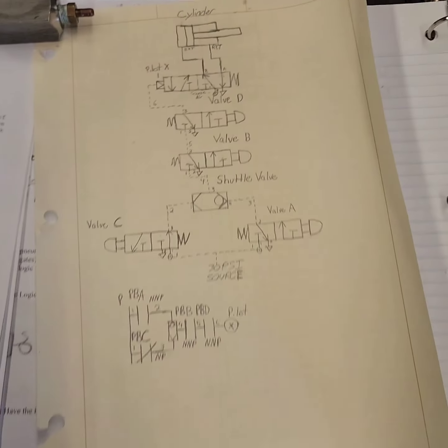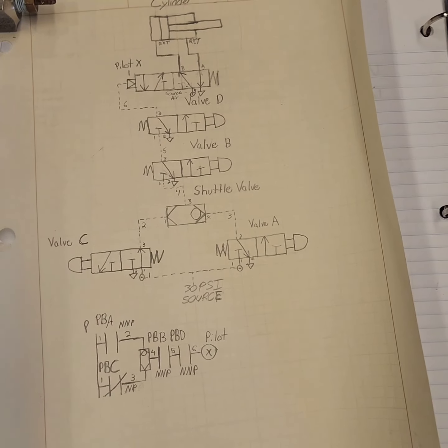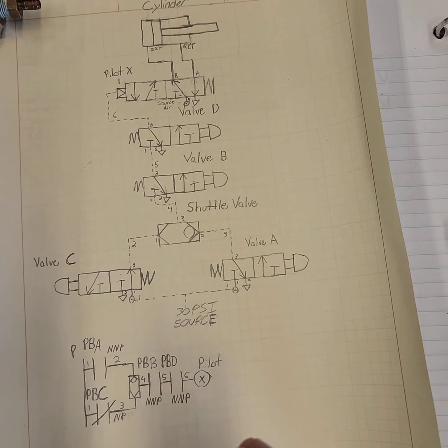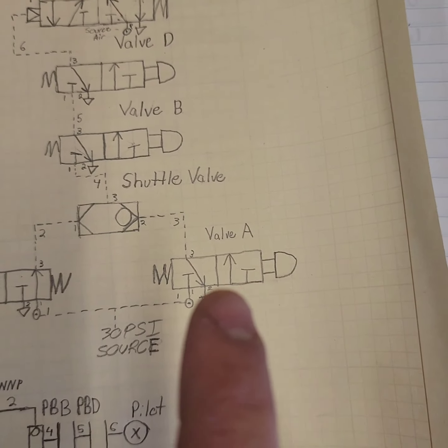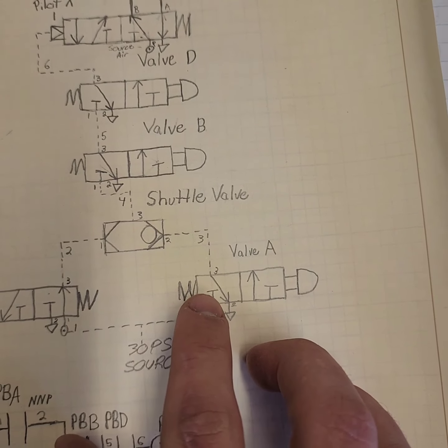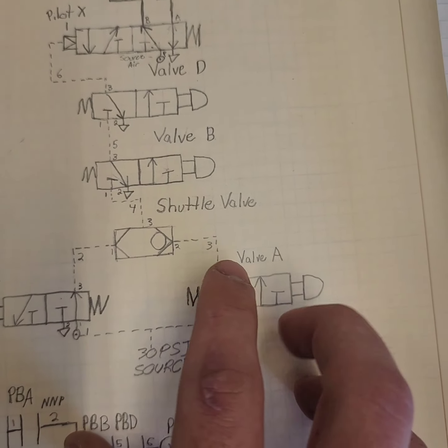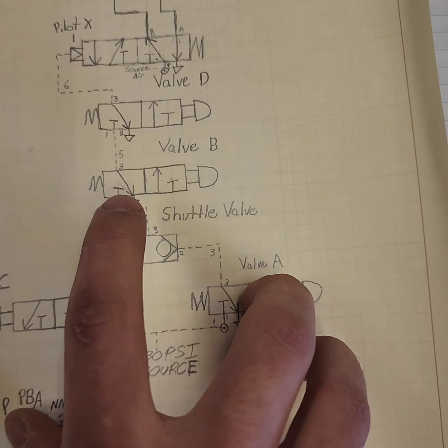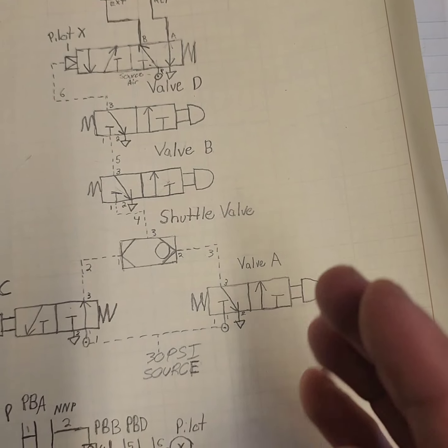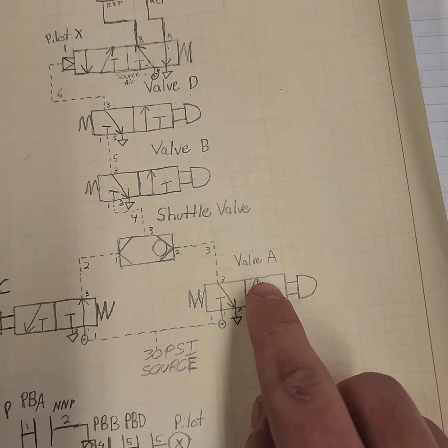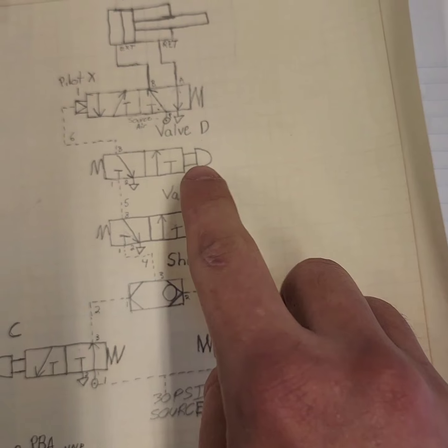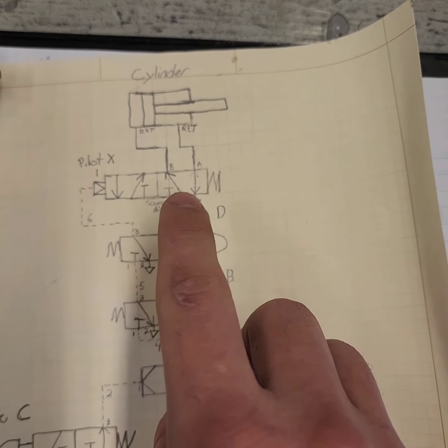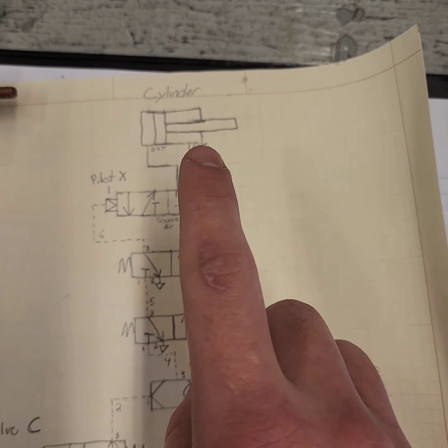Now we also had to create a circuit diagram for this, and so we used push button valves to replicate each letter A, B, C, and D. And so you have the normal A is going to be normally not passing, so you have to press that, and then you have that ORed in with the B and D, which are both also normally not passing. So those have to be pressed in order to let it go. So you have your A and your B and your D, and that will send a pilot signal out to X, which will turn on the control power, causing the cylinder to retract.